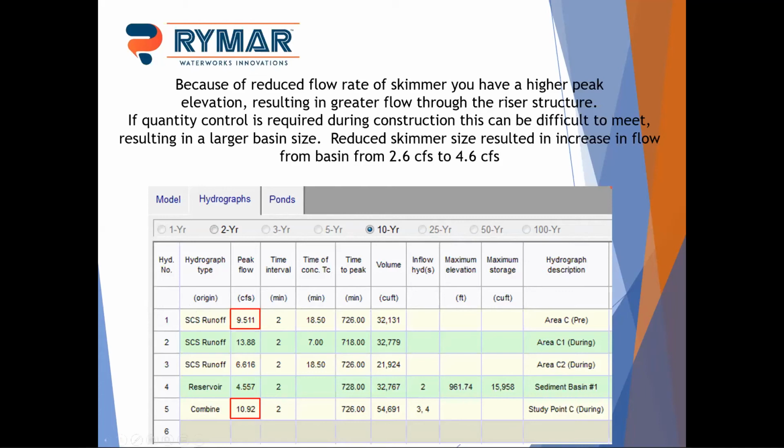The third-party testing has shown that the constant head with the skimmer does not necessarily result in a constant flow rate. So any flow rates that I refer to in this presentation for our skimmer are based on testing that was done by TRI Environmental to confirm the actual flow rates for each skimmer and each skimmer orifice configuration.